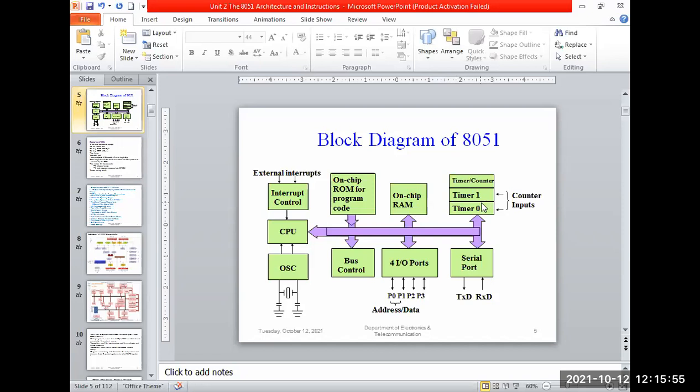How do we decide that it is 16 bit? Because while designing the 8051, they designed the timer with a size of 16 bit. That's why I'm saying the size is going to be 16 bit. If you use this, what is the maximum count that can be counted by the timer? It depends upon the size. So 2 raised to 16, that belongs to 4 times F in hexadecimal. In decimal, it is 65,536. That is the total count that can be held here.